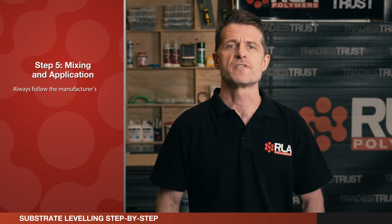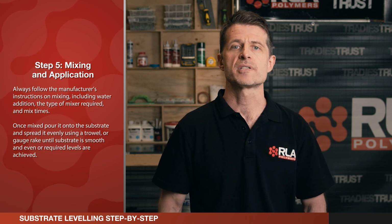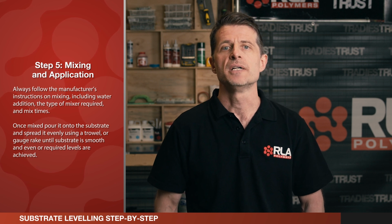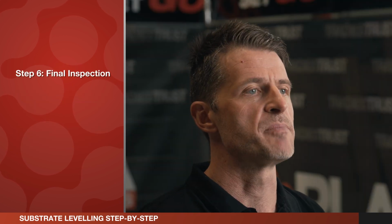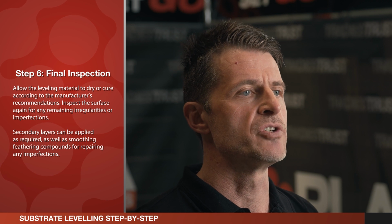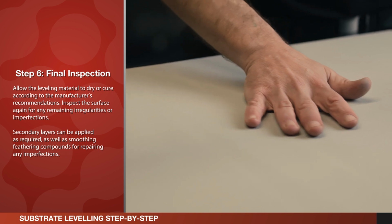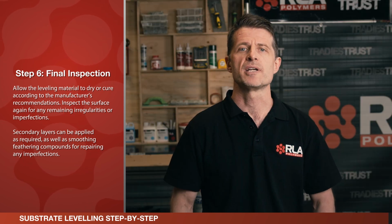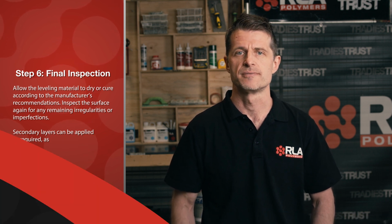Always follow the manufacturer's instructions on mixing, including water addition, the type of mixer required, and mix times. Once mixed, pour it onto the substrate and spread it evenly using a trowel or gauge rake until the substrate is smooth and even or required levels are achieved. Final inspection. Allow the leveling material to dry or cure according to the recommendations. And once it's dry, inspect the surface again for any remaining irregularities or imperfections. Secondary layers can be applied as required, as well as smoothing or feathering compounds for repairing any imperfections.